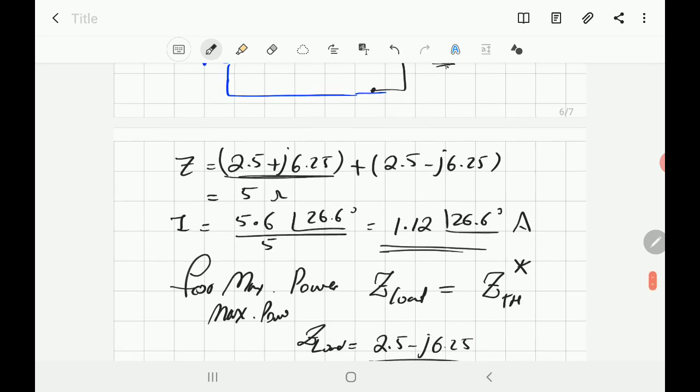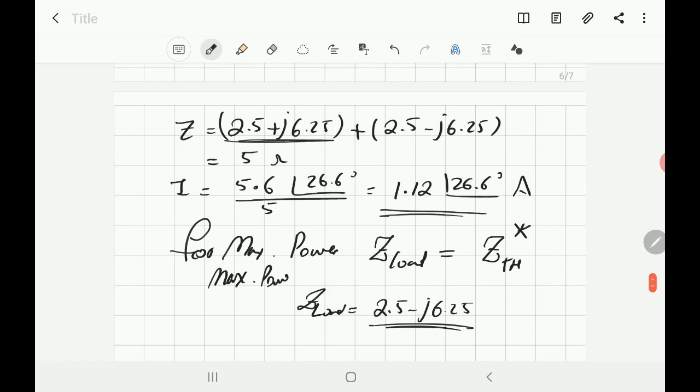So actually what you have here is the impedance that will get maximum power. Because when you make the conjugate, you observe that the imaginary part will be cancelled. When you cancel it, you minimize the value of the impedance. And as you know before from DC circuits, to get the maximum power, the resistance of the load should be equal to the resistance of the source.